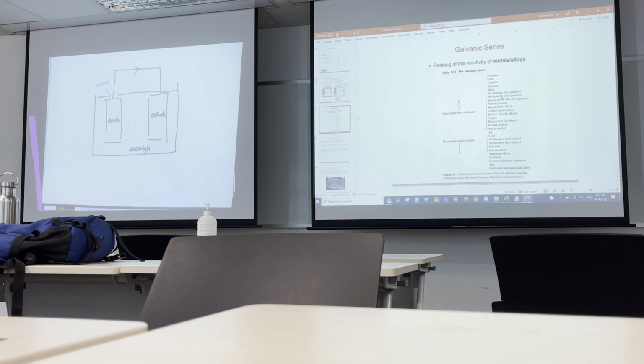No, you put the aluminum as the anode. You make it oxidized. So you create more of an oxide layer on the aluminum so that in future it protects the aluminum from further attack. And in fact, for those people who are looking at the anodized thing, because of thin film interference effect, some of the aluminum will have a color, a bluish tint, based on optics. So again, these are small little tricks that people use to protect material.